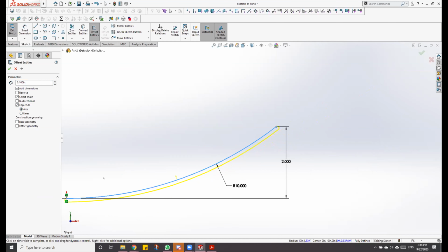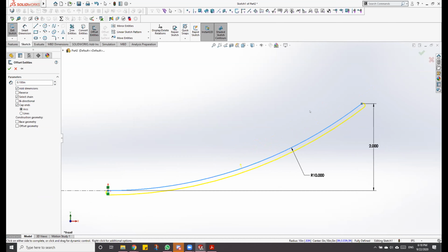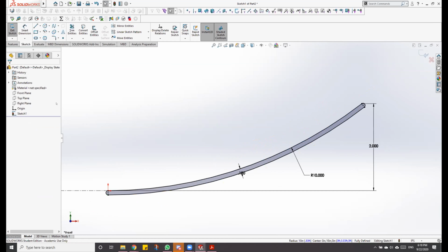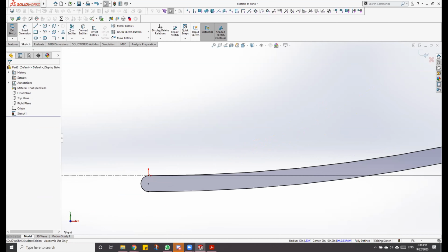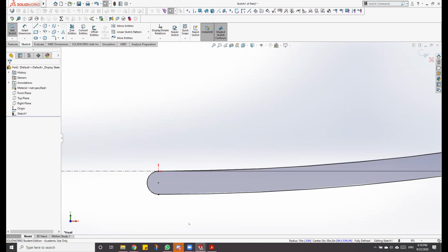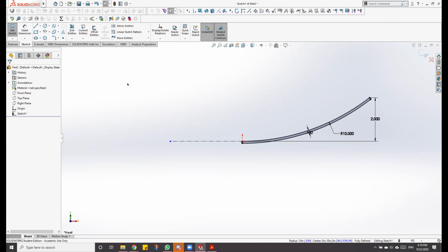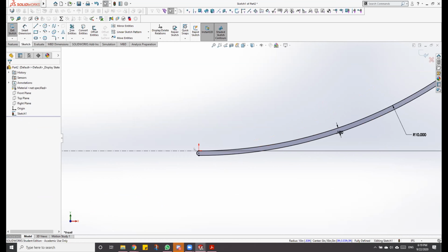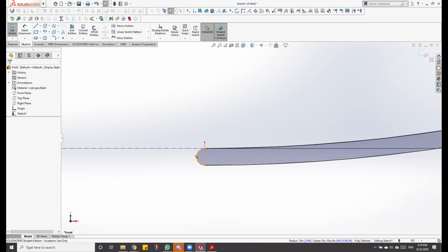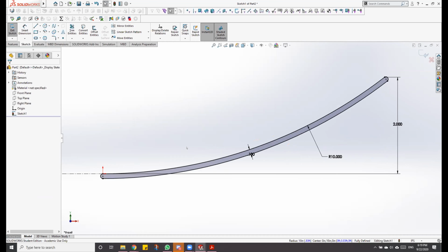Is everybody keeping up? Do you guys see what I'm doing? Okay, I'll just leave that and press OK. Now, in my case, I am going to be rotating this to create that round strainer. So we're gonna cut this arc because this is a closed feature. And actually it might merge. Let's just see how it works. I don't remember how I made the last one, so we're just gonna go with it.